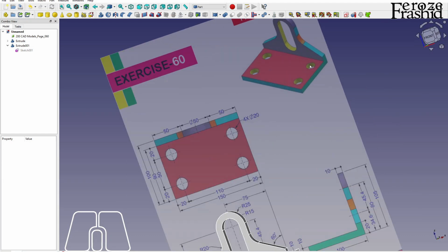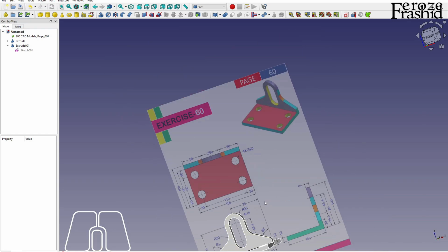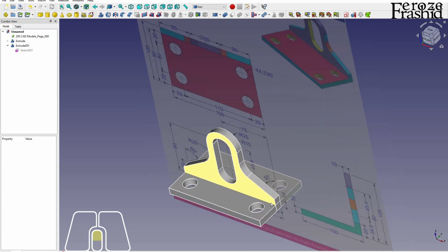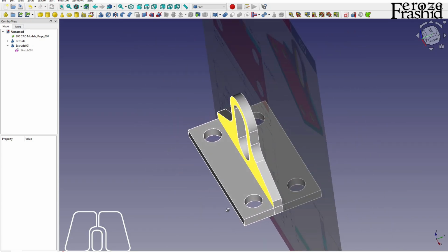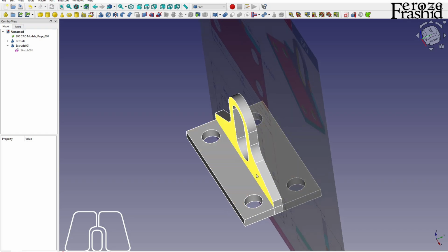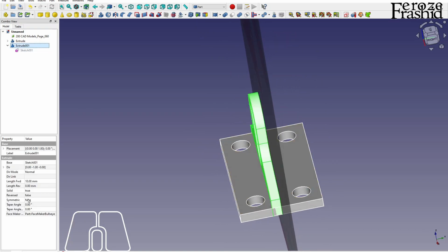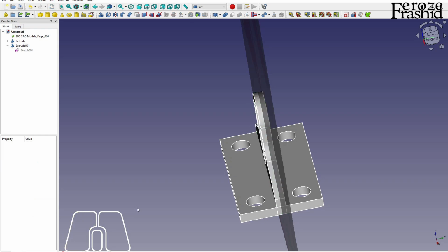Now this picture says that object, that wall, is at the end of the plate that we built earlier, but because we built this sketch in the middle, this wall is now in the middle. Actually, it's not in the middle, it's a little offset because we did not get symmetric. So let's go ahead and make it symmetric.